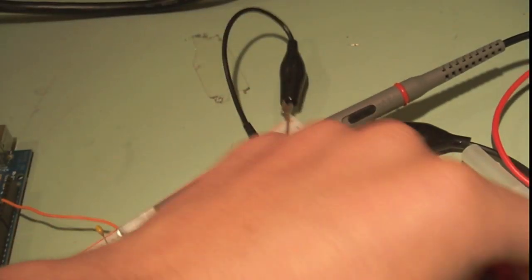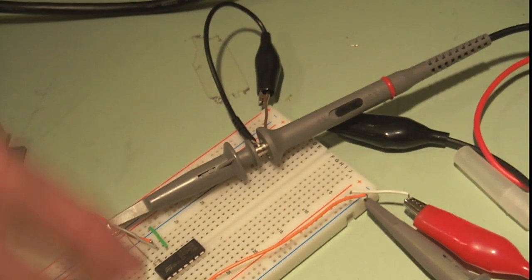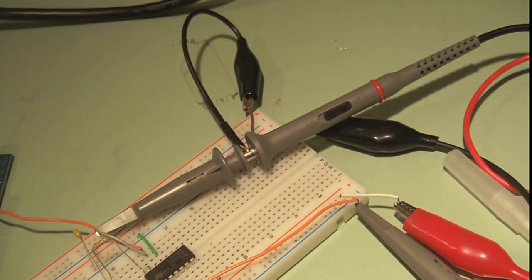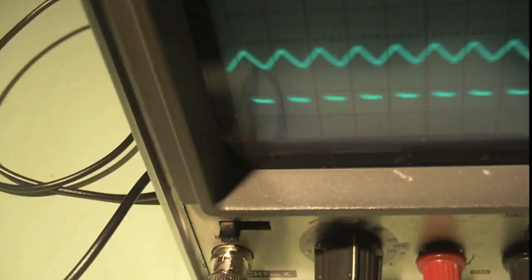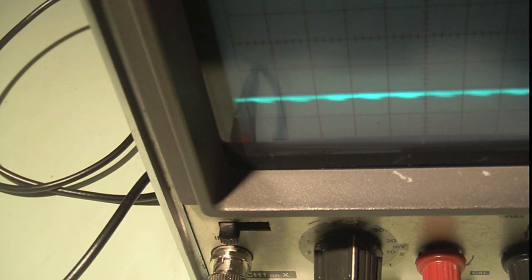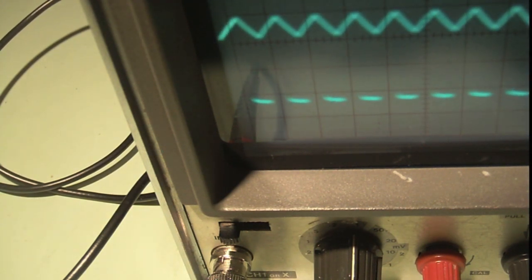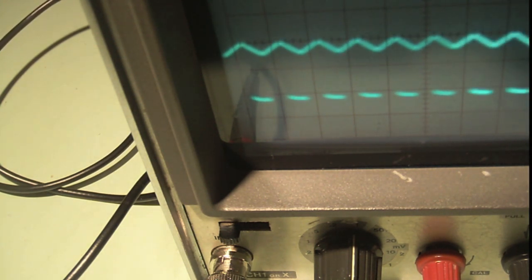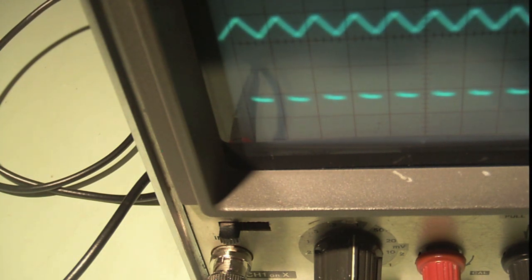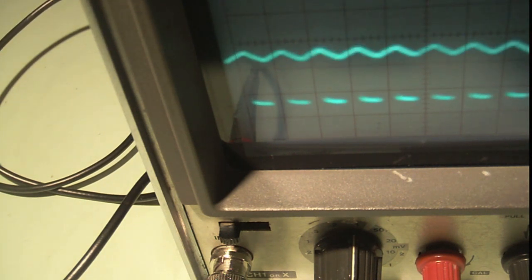But before I go, one quick thing: the scope ground, since we're using 2 channels, this is just a quick scope hint. Only one ground has to be connected because both grounds are connected. But remember for this LM324, also, this supply rail issue, if we set this to be DC coupled, and I'm going to turn down the voltage, you can see the actual voltage that we're getting goes down when I lower the voltage. Between 10 and 15 it's the same, and I lower it down to 5, and it starts to drop, okay?